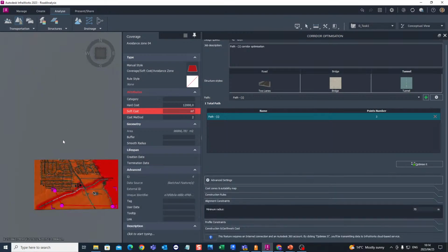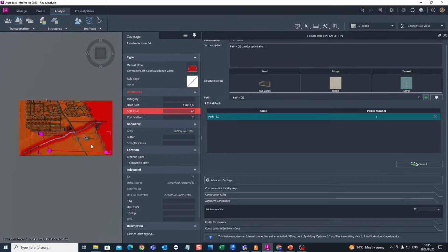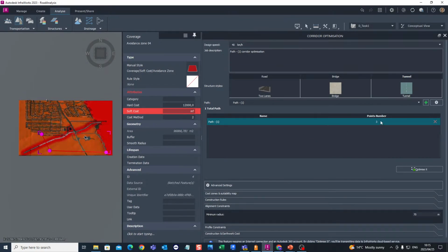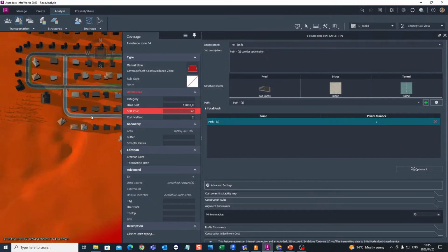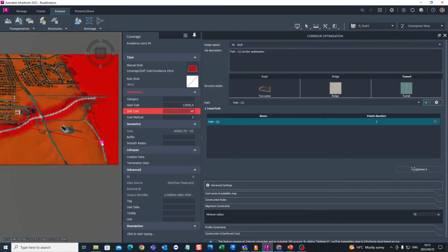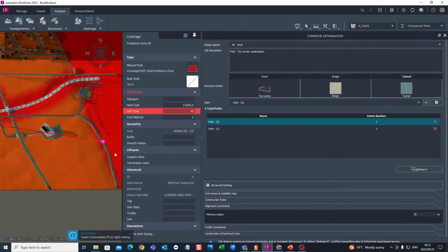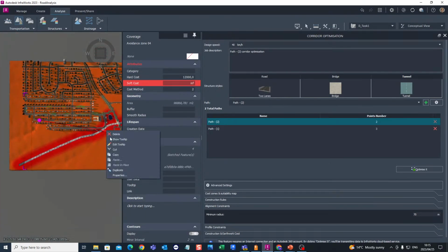And then of course you can do different paths. So that's the typical path that you'd like it to go, but you can also use different paths, and then you would just create another one. So we've got path 1 here. If we do path 2, then we can do the same thing. We might say we want it to go from a different beginning, and hook up to the same sort of road here somewhere. Exactly the same way as we've done before, you can add PVIs.